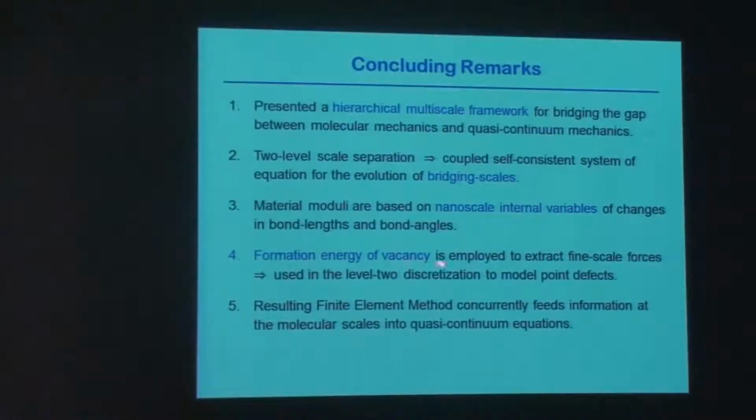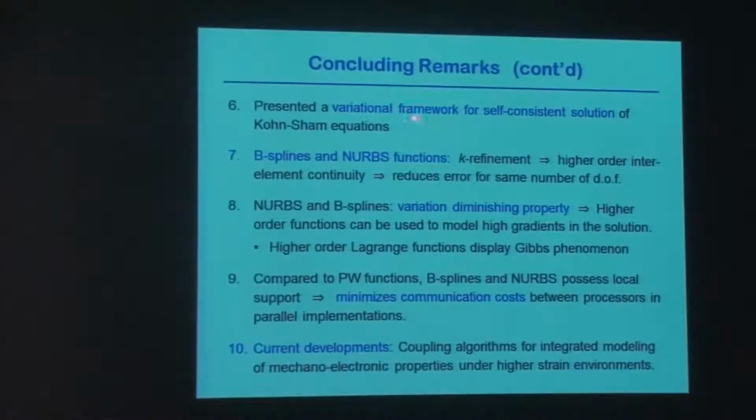For the formation energy of vacancy, we employed this idea that exists in physics, and used it to extract the fine-scale force field, which we then embedded here to solve the problem locally. The resulting finite element method concurrently feeds information at molecular scales into your quasi-continuum equations. And this is a variational framework, and I've also shown this framework for quantum equations.